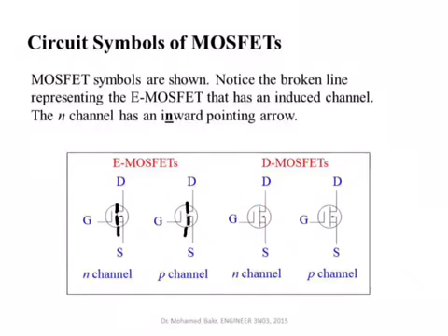It's just to show you that when VGS is 0, we can still have current flowing from the drain to the source. And now if this is an N-type MOSFET, then current will be flowing from the drain to the source. It's controlled by the voltage across the gate. This is an N-type material, this is an N-type material, while the substrate is a P-type material. The other type of D-MOSFET is a P-channel, which is not as commonly used as N-channel. This is a P-type material, this is a P-type material.